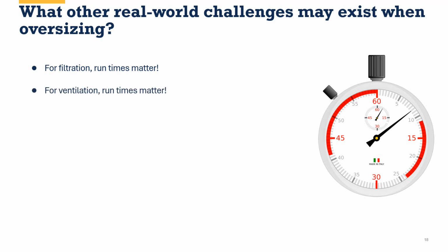For ventilation, just like with filtration, if we're either integrated, meaning a duct from an HRV, ERV, or a fresh air duct is coming into our system, or if we're just using our control strategy to control a separate ventilation system at the same time that we control our central air handler, guess what? If that air handler is not running, then neither is our ventilation.